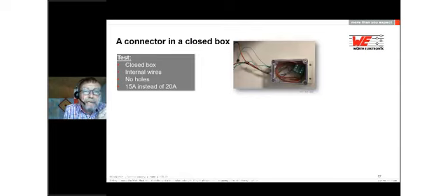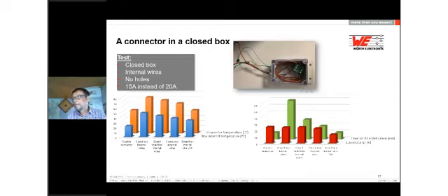So now we do something else. We use 15 amps instead of 20 amps, or you can also use a connector which is suitable for higher currents. On the other side, it's the same thing. Then the time for stabilization goes down very fast, and the connector is not warmer than outside of the box. So that means the best thing to reduce the heat if you have a closed box is to take the biggest connector which is possible and the biggest cable section which is possible and put the wires outside. Then you are on the best way for your application.